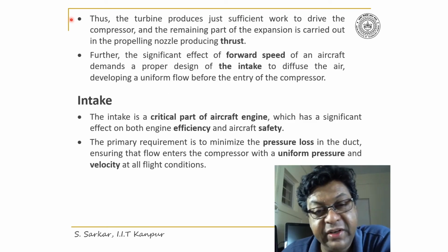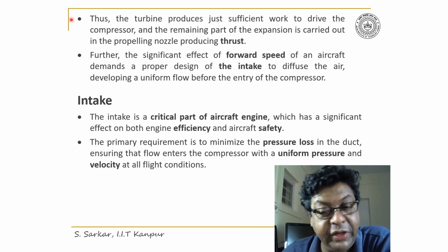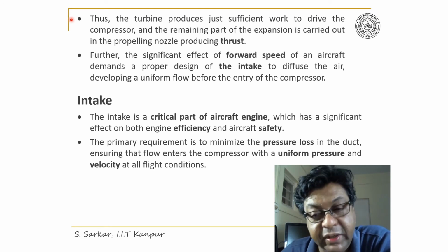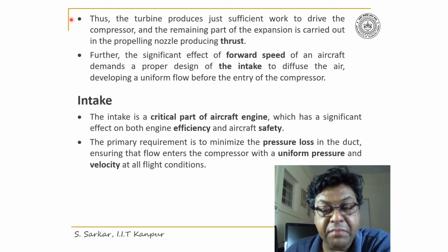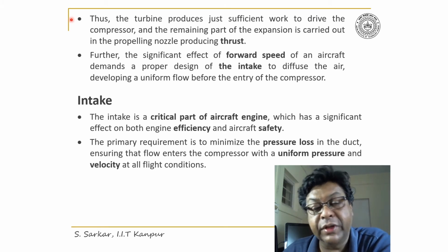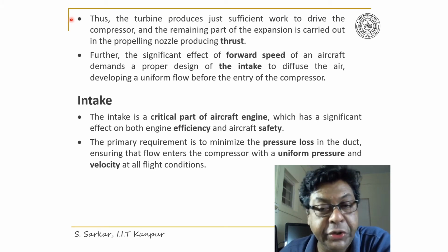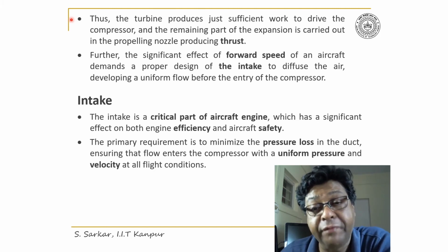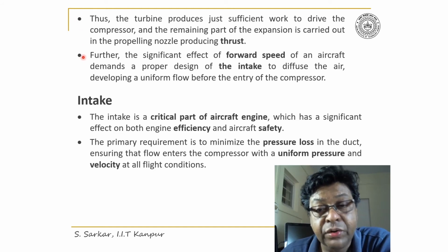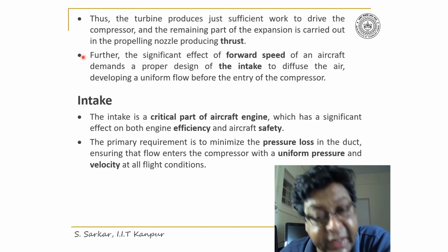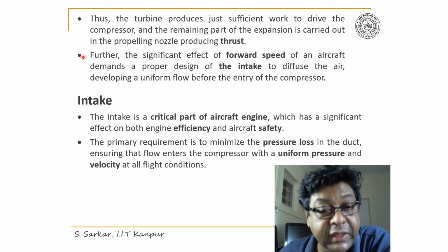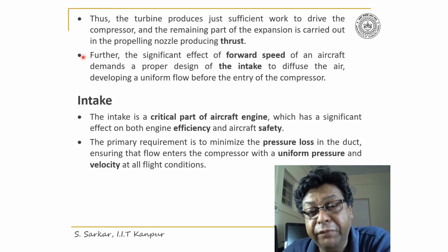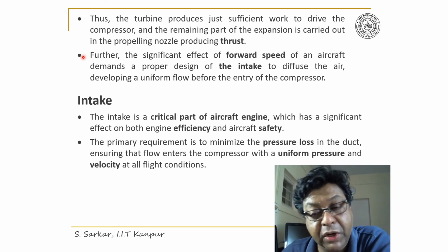Thus, in a turbojet engine, the turbine produces just sufficient work to drive the compressor, and the remaining part of the compressed gas is expanded through the propelling nozzle to produce thrust. Further, the significant effect of forward speed of an aircraft demands a proper design of the intake to diffuse air, developing a uniform flow before the entry of the compressor.